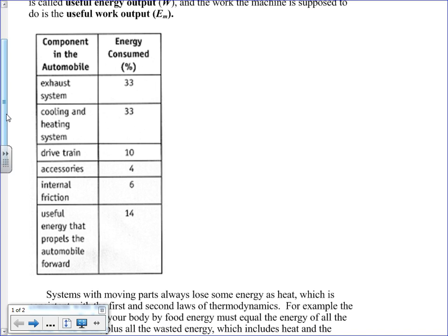So what you have to have on your car is a big pump called a water pump that pumps coolant through the engine block and absorbs heat energy from the engine, takes it to the radiator, and you have a fan there that blows cool air across the coolant, and that vents the heat outside of the car. All of that heat came from the energy in your fuel. It isn't doing any useful work. So you've got heat loss there. You've got energy being used to run the pump, to run the fan, all of that kind of stuff. Is any of that propelling the car forward? None.